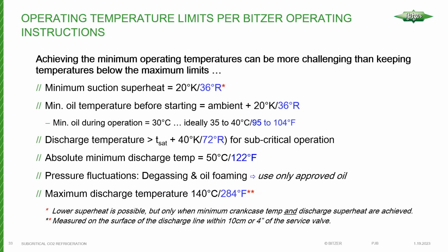So, minimum oil temperature before starting. Make sure those crankcase heaters are on. They should have that oil temperature warmed up sufficiently, for example, 20 Kelvin or 36 degree Rankine above the ambient temperature. And what this does is it limits the flow of refrigerant to the oil, it prevents it to some extent, but never eliminates it.